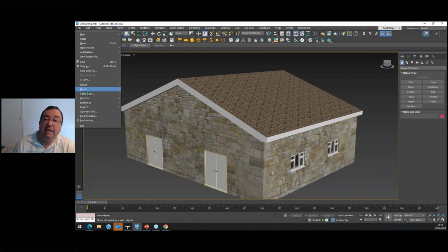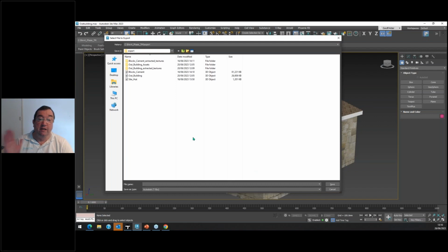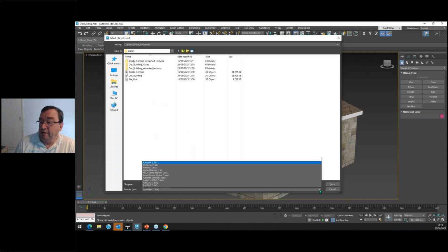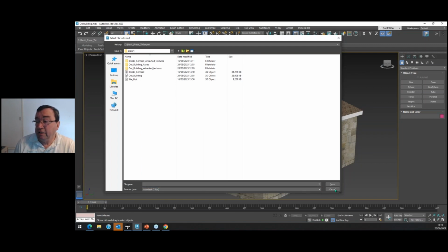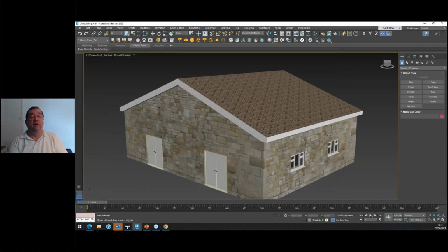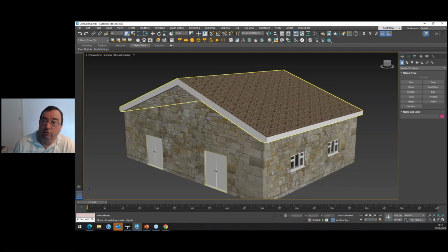I could indeed export out of my AutoCAD, or out of my 3D Studio Max as either an FBX here, or indeed I can use the Unreal Datasmith again. I tend to like using FBX because very often I can export an FBX and embed the media that's within the file. Not so much on this project, but a lot of projects I would use that.